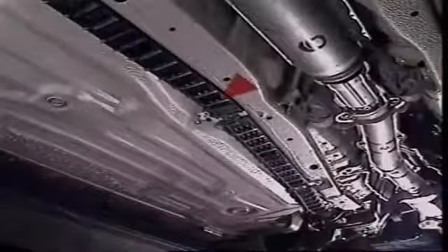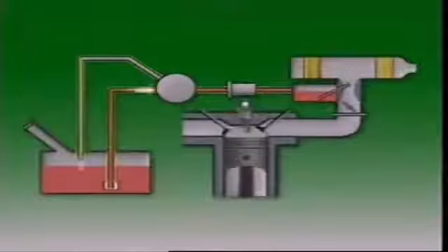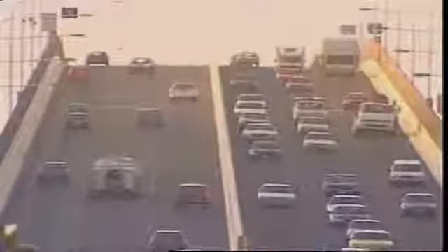Fuel lines are usually made of metal tubing or synthetic materials. A fuel supply line carries fuel from the tank to the engine. A return line may also be provided to allow excess fuel to return to the tank. This helps prevent the formation of vapour that can occur in the fuel supply during hot conditions.